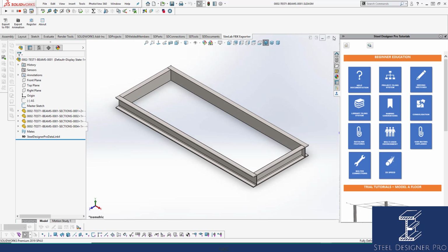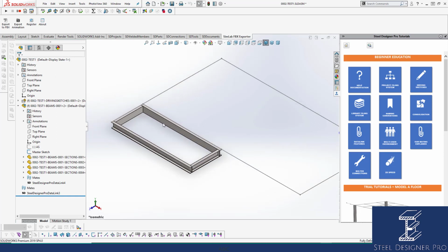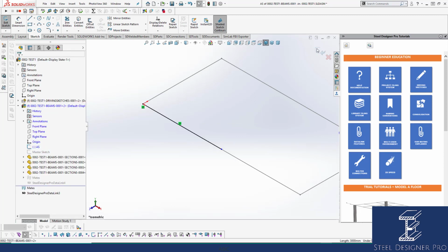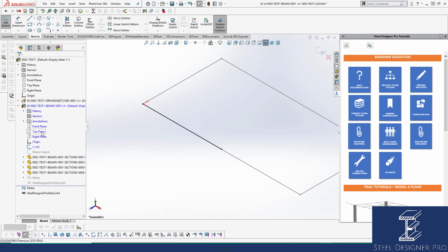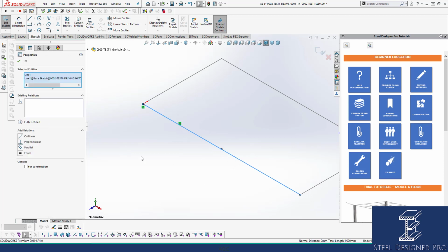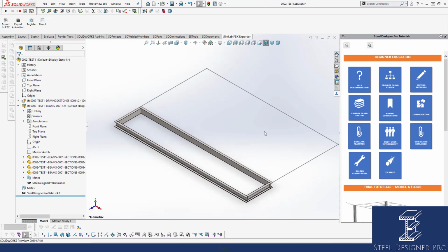Now we're at this assembly level, which is the welded member level. I've just closed it off and now we're at the zone level. So it means now we've got this welded member and we've got an attachment sketch. So I'm going to attach that attachment sketch by clicking on the sketch segment and editing the sketch feature. I should say, let's go back and do that again. Edit the sketch feature in context, select the sketch segment, select the driving sketch segment underneath and make them equal like we did before. And you'll notice the platform now has updated its length.